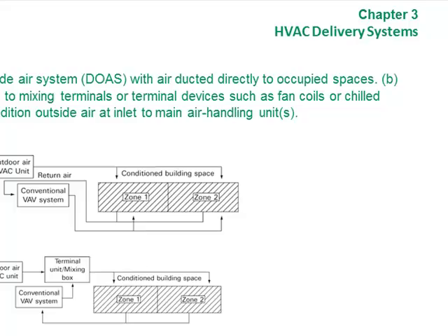They both have compressors in their unit. They differ in their means of rejecting the heat. The heat pump rejects the heat to the water delivered by a piping system, and the PTAC rejects to the outdoors, so it just pushes it out through the air-cooled condenser. The PTAC must be located on an outside wall, or a rooftop, so it can't be in the middle of the building somewhere.